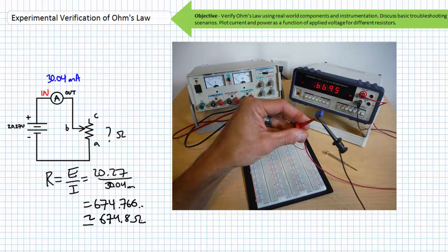When we remove the potentiometer from the circuit and check the resistance between the two terminals we used, our ohm meter states we're extremely close to this value at 669 ohms. You at this time should be absolutely convinced that Ohm's law is not just purposeless busy work, but a real and observable property of electrical circuits that can be readily applied to circuit analysis.